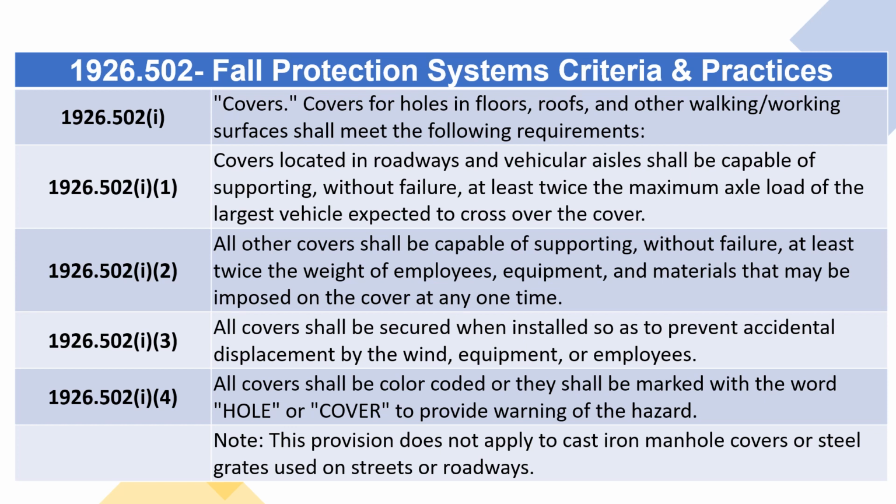All covers shall be secured when installed so as to prevent accidental displacement by the wind, equipment, or employees. All covers shall be color-coded, or they shall be marked with the word "hole" or "cover" to provide warning of the hazard. Note: this provision does not apply to cast iron manhole covers or steel grates used on streets or roadways.